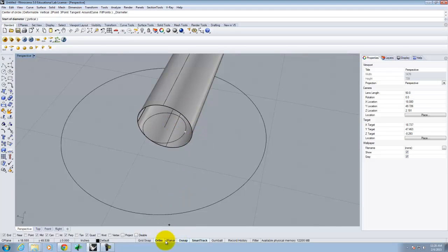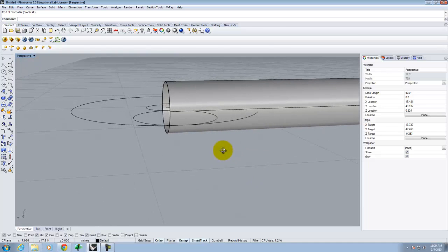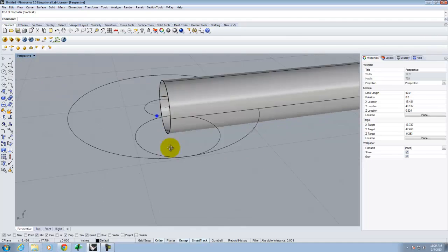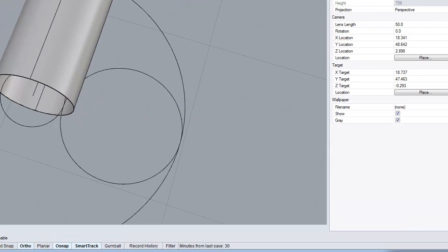Now I've chosen to turn on what's called quadrant snap, which basically means on a circle it divides it into 4, north, south, east, and west, and lets you snap to those 4 corners of a circle, even though circles don't have corners, but you get the idea, right? So I have quadrant snap checked, and I'm going to snap from here to there. And you see how it builds a nice circle for me based on that diameter. Okay. Could I mentally do the math, 1 3/4 minus 3/8, and come up with whatever it is, 1 inch and 3/8, right? Yeah. For this, sure, but I would rather just do it from the diameter and not have to do any math.